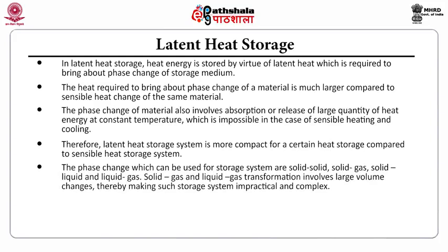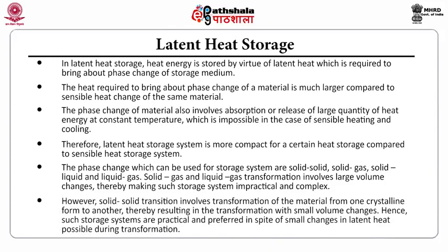The phase changes which can be used for storage systems are solid-solid, solid-gas, solid-liquid and liquid-gas. Solid-gas and liquid-gas transformations involve large volume changes, thereby making this system impractical and most complex. But solid-solid transition involves transformation of the material from one crystalline form to another, resulting in the transformation with small volume changes. Hence, such storage systems are practical and preferred in spite of small changes in latent heat possible during this transformation.